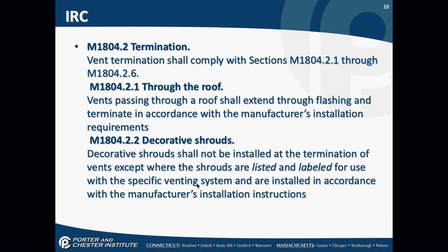Vent termination, that's where it ends. Okay? What happens above the roof? What happens where it ends? It tells you to look at sections 1804.2.1 and 1804.2.6. Vents passing through a roof shall extend through the flashing and then terminate in accordance with the manufacturer requirements. Okay, you can't install decorative shrouds. In other words, you can't decorate the top of the vent to make it look like a pine tree or something, unless it's listed or labeled for use. And again, refer to the manufacturer's installation instructions.